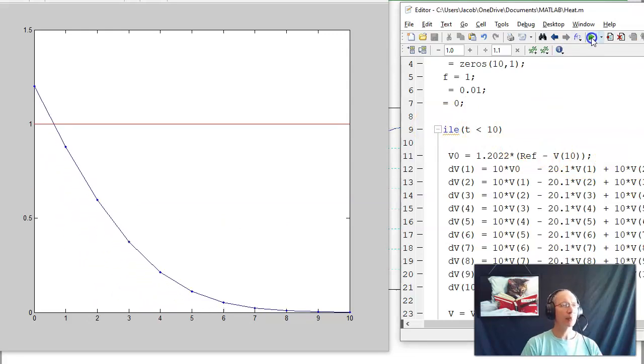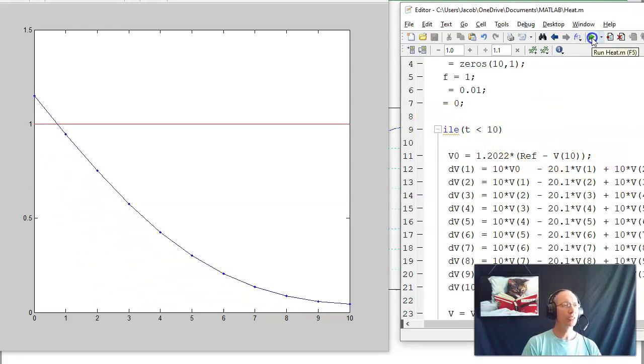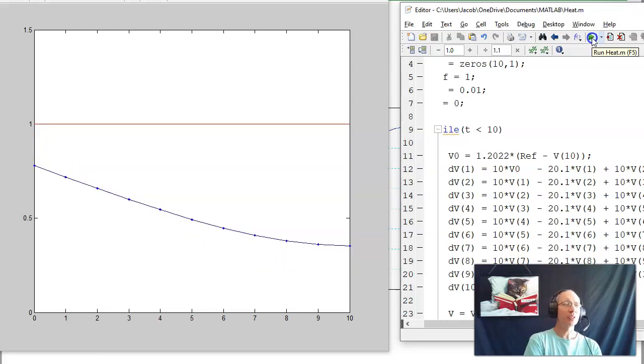So give it a step input. It warms up, and then settles out without any overshoot. That's the power root locus. I got this response. I didn't have to iterate.